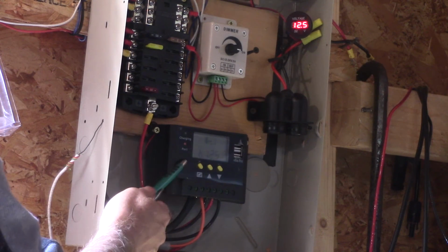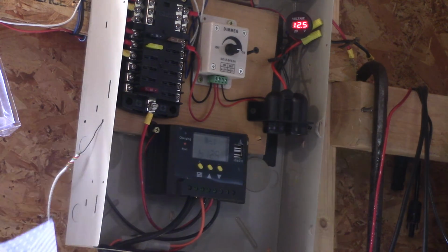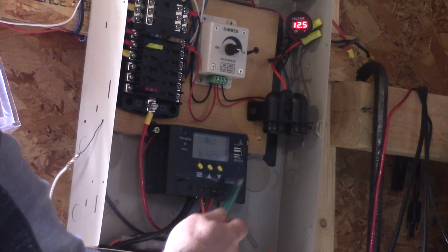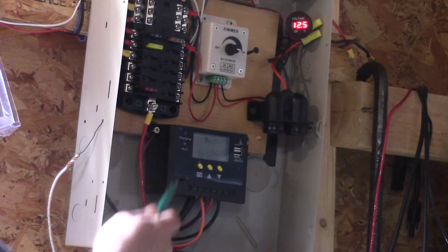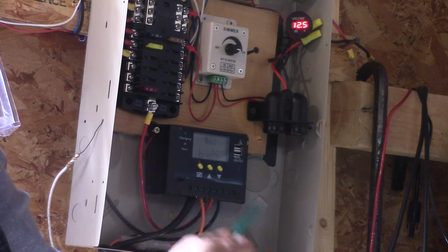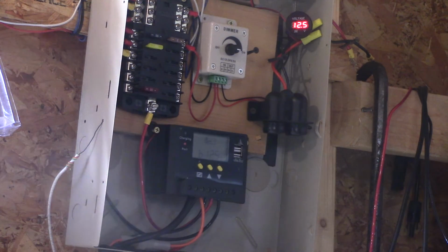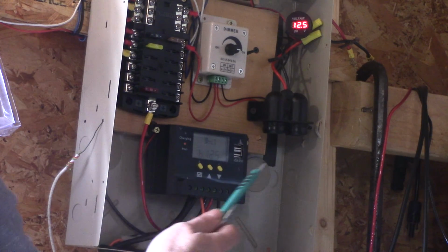The 3 10-watt LED light circuits, or lights, are a total of 30 watts. That gives me a total of 60 watts. So 60 watts divided by 12 volts is 5 amps. Since my charge controller is rated for 10 amps in and on the load side 10 amps out, I can run that whole circuit off the load side of my charge controller, can't I? Since it's rated for 10 amps, we came in at 5 amps, boom, we're good.